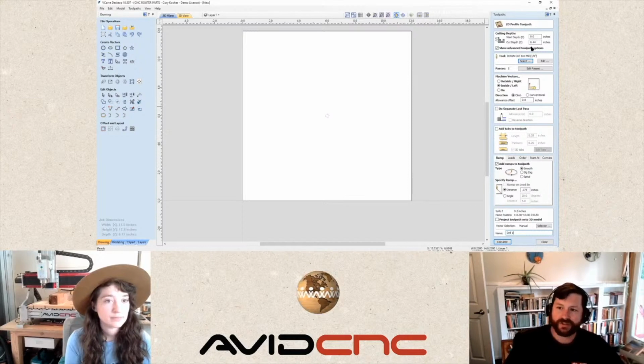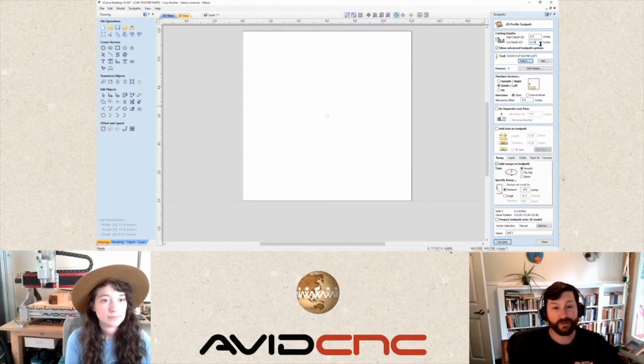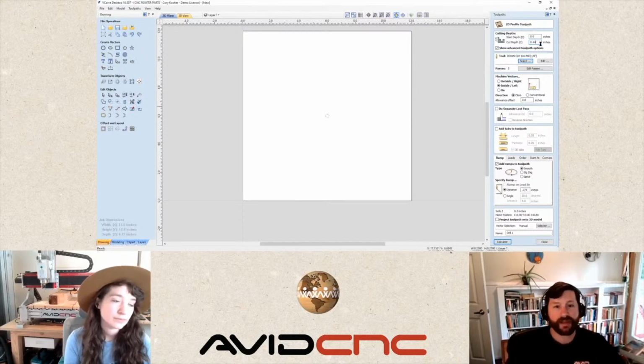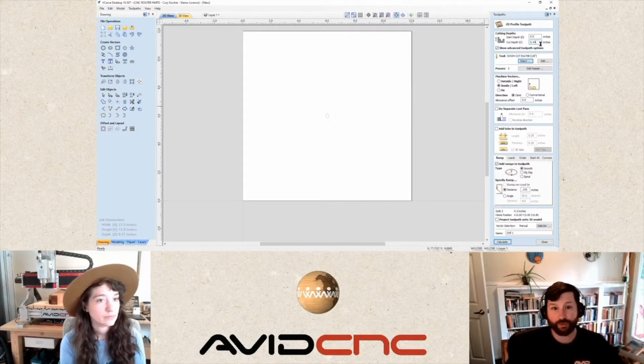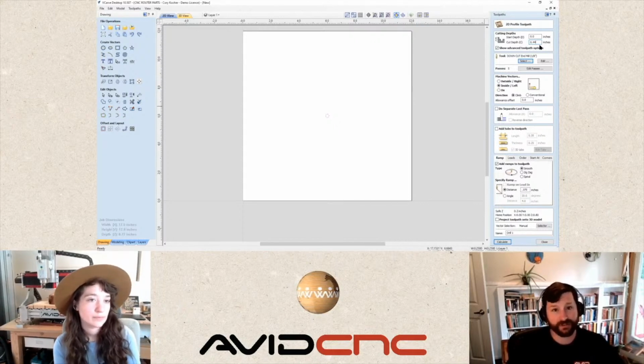You'll also notice here that I've stopped our cut depth at 0.44. Essentially this program is just going to get us down to 0.44, which is just over halfway through our material. I do this because I want to potentially give us an opportunity to help evacuate those chips because of the down cut tool. We're using the down cut because we want to preserve that top veneer, but we need to recognize that when we use a down cut, we're encouraging the chips to stay in the cavity we're creating. By having an opportunity to maybe remove those chips with compressed air, or change to a different tool that pulls them out as we go deeper in the material, that's why I only go about halfway through on this first one.